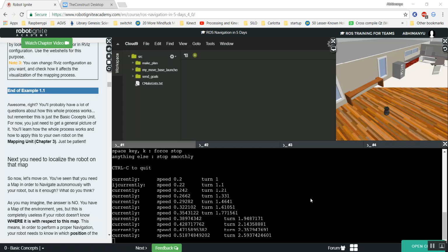Remember, where exactly is the person or the robot standing in the map. You need to be very sure about that in order to go from point A to point B. In a sense, you need to find out point A to plan the path to point B. That is what is called localization. So the next step is actually localizing the robot.